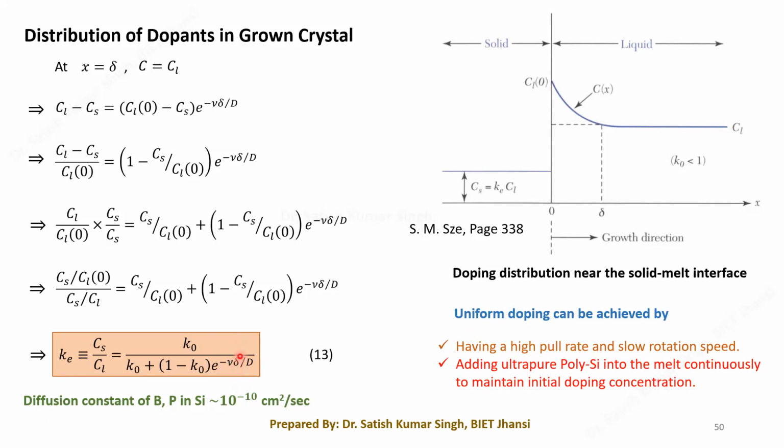And if we want to increase the stagnant layer thickness, we want it to be a motionless melt. Obviously the spinning rate should be slow. So try to think of it. If we have slow spinning rate, then obviously the stagnant layer thickness will be more.